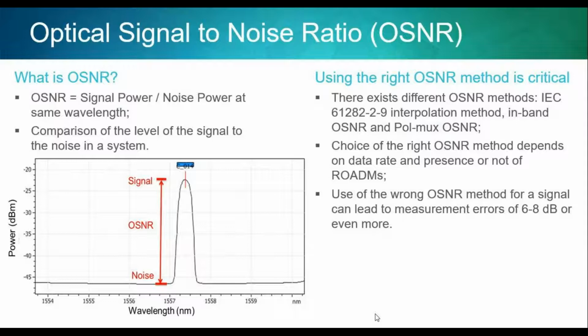As you're amplifying the signal, you will try to flatten that as much as possible with those gain flattening filters at the output of those amplifiers. So depending on the quality of those, it's not necessarily the power, but the quality of how those EDFAs are built with regards to their flattening filters.